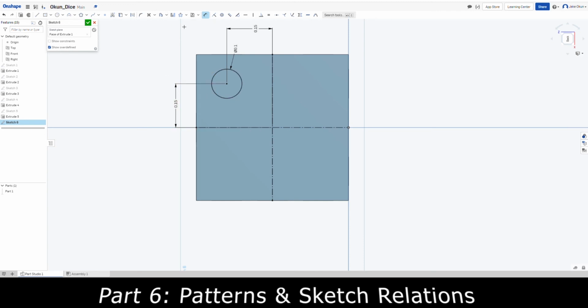We're actually going to use the mirroring technique again, because I find that that's one of the most powerful techniques you can use in Onshape. You'll notice that when you're creating custom parts for robots and different things, that when you're creating something that's either going to be 3D printed or cut out with holes for bolts or screws or anything you're going to use, you're going to continually use the mirroring technique. So instead of doing the circular pattern tool, we're going to do the mirror technique.